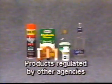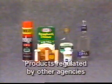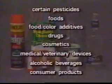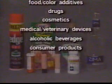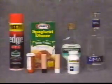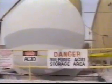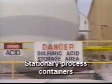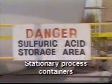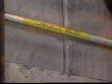Third, labels are not required on products regulated by other agencies. This includes certain pesticides, foods, food or color additives, drugs, cosmetics, medical or veterinary devices, alcoholic beverages, and consumer products. And finally, signs, batch tickets, or placards can be used in place of labels on individual stationary process containers as long as the information is easily accessible to workers. You should also know that the federal standard doesn't require labeling on pipes or piping systems, but some states do require it.